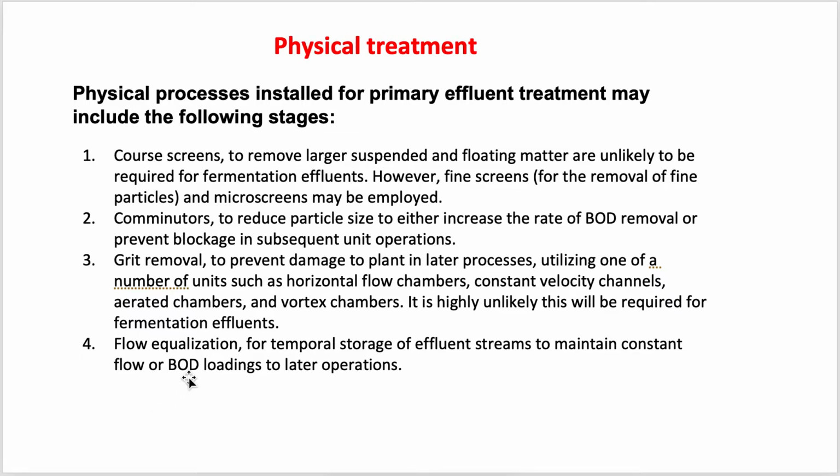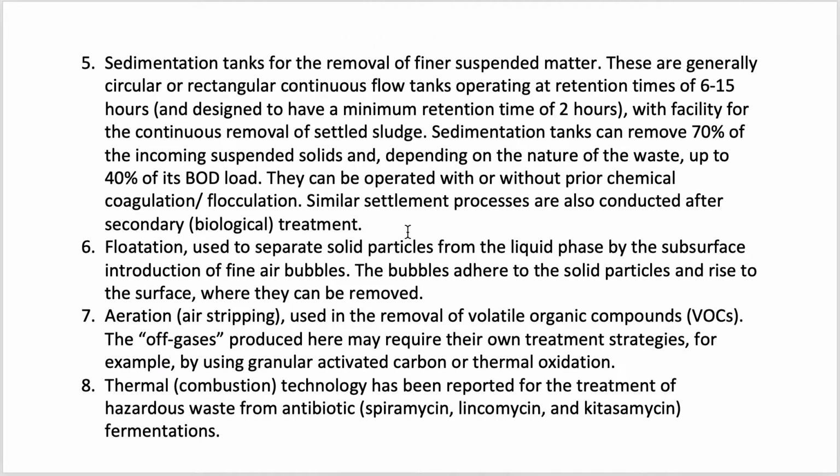Then flow equalization. Flow equalization is necessary for temporal storage of effluent streams to maintain constant flow or BOD loadings to later operations. Then sedimentation tanks for the removal of finer suspended matter. If the effluent contains fine suspended matters, sometimes they are left for a defined amount of time, for example several hours.